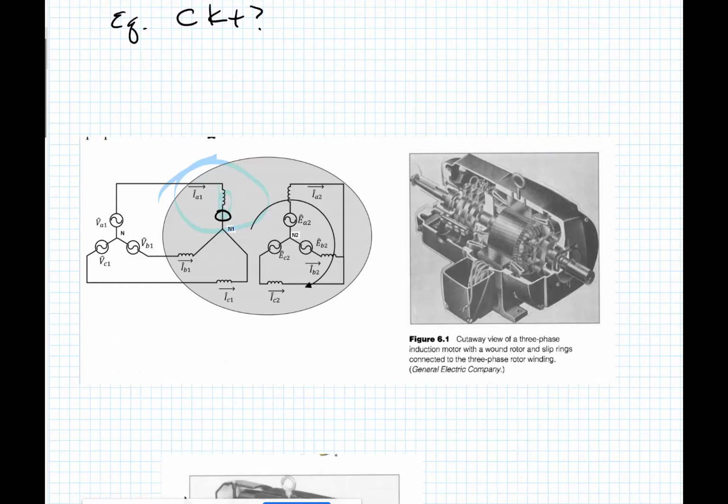So what do we have? We have a winding on the stator. Typically, they call this R1. There's a leakage, jX1. So we're back to this transformer. We have to do the full circuit. There's a magnetization, so there's going to be a magnetizing branch, jXM.